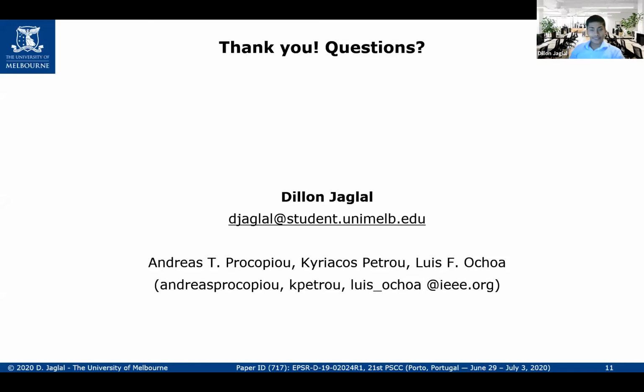So a lot of work from my team is actually being produced on this. I will really be happy to point you to some of those papers. And yes, we are seeing some problems especially at the medium voltage level. Not so much on the voltage side, but more on the thermal side at the medium voltage level. And to answer the question of when, we're seeing it, from my memory, I'm calling from memory here, between 30 and 50% PV penetration. Bear in mind, right now we're at 20% more or less.